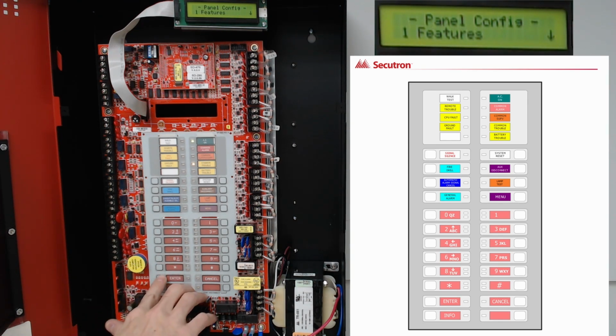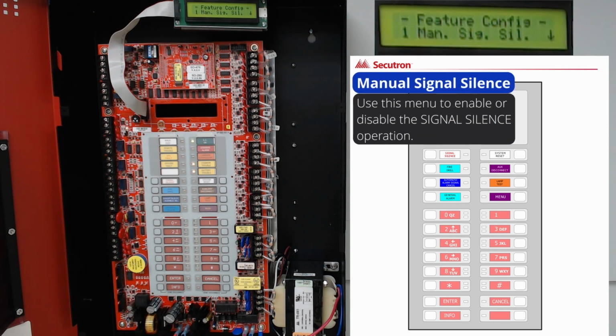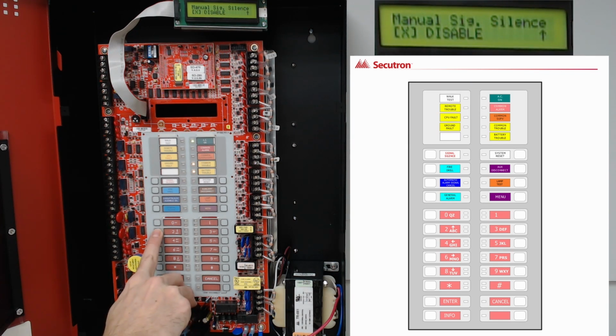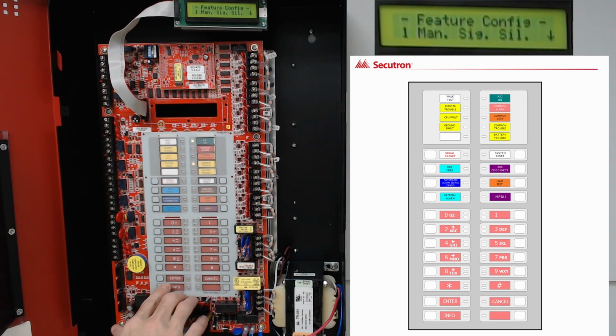On Features, if we would like to enter it, select Enter when it's visible on the screen. Now we've entered the Features Config area. Option 1 is Manual Signal Silence. When on the Manual Signal Silence option, if we press Enter, we have the option to leave it enabled as default, or by pressing down and hitting the left or right cursor arrow and applying the X, we can also disable it. By pressing up, we can now see that it is no longer enabled. By pressing Cancel, it'll exit back out to the previous screen.